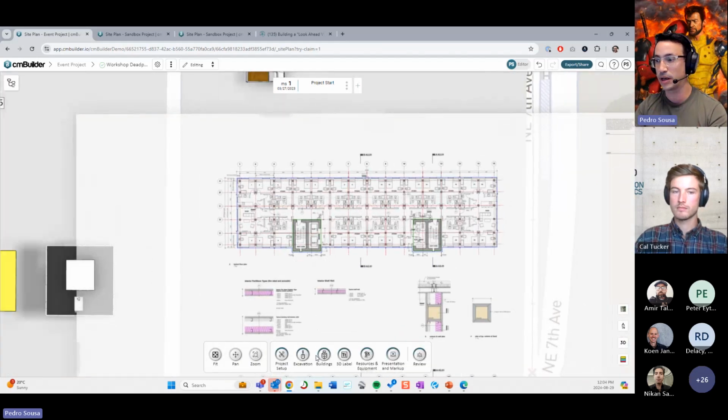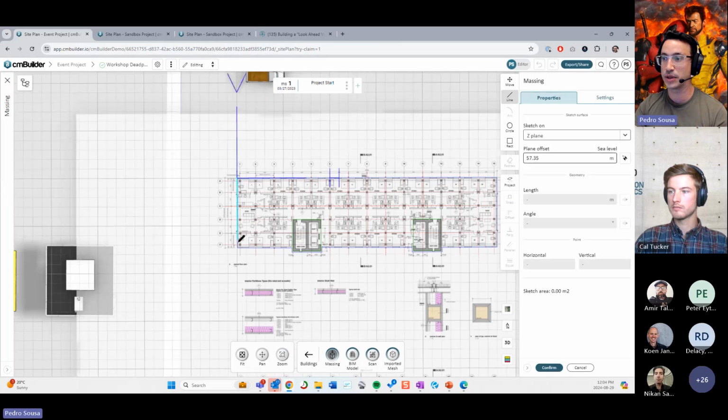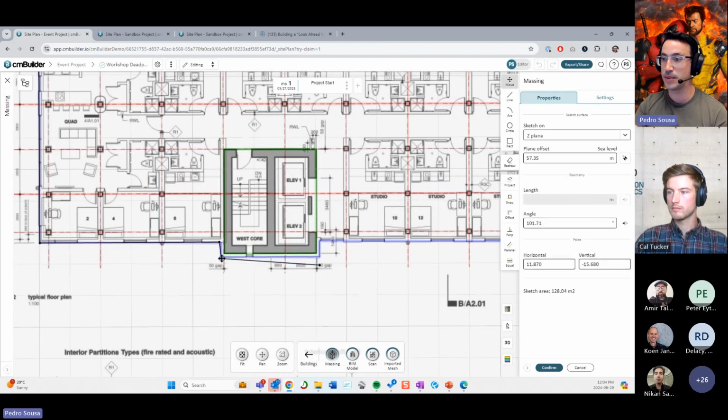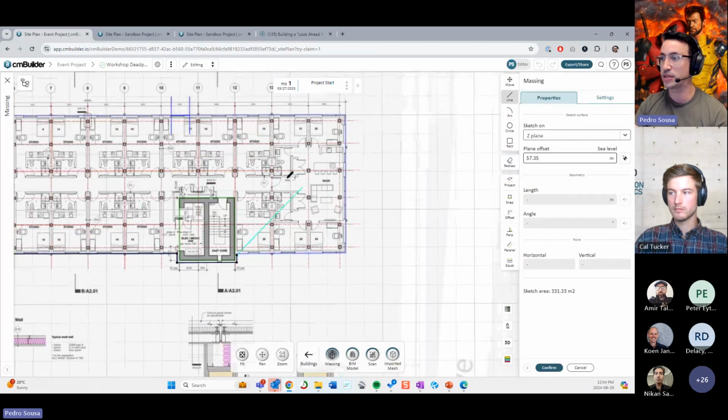So I'm gonna really quickly over here create a simple massing that is basically one single extrusion from a sketch, right? So you can see instructions about that in our user guide. And another interesting thing about this is that every time you're drawing a sketch, you should be working with a sketch that is looking from the 2D view, right? And you're gonna start placing some points, and if you hold Shift while you're doing this, the increments of your lines will be in 45 degrees, so it's easier to draw the shape, right?